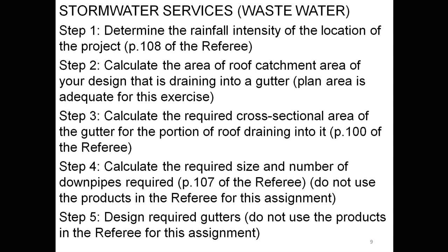So what we're dealing with here is a much bigger scale thing, and if you've got valley gutters going from the front to the back, and the low point is at the back, then you would have some sort of overflow system there, or if it goes into another box gutter which takes it to the edge, then at the edge you will have some sort of overflow system. But generally, in these kinds of big roofs, because everything is so big and you're unlikely to have leaves getting in there, you have commercial maintenance regimes and so on. This kind of stuff shouldn't happen unless we get more rain than has ever been recorded in the past.